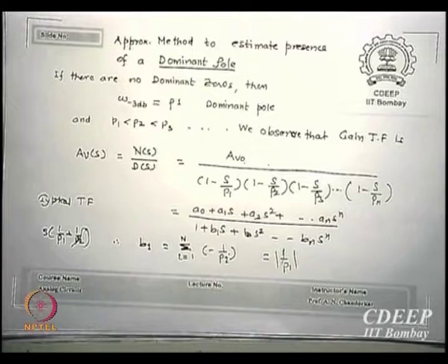Now how do I get this P value? This is my next question. To get P1, I must somehow calculate it. P1 is related to what in the normal case? We have discussed that P1 is nothing other than related to time constants. So if there is more than one capacitor coming into the picture, we must calculate the poles occurring due to all such capacitances and the loads associated with them, okay, and then sum all of them like this. If I get that 1 upon tau average, which I am going to do, I will get my poles. Here is an example for that.